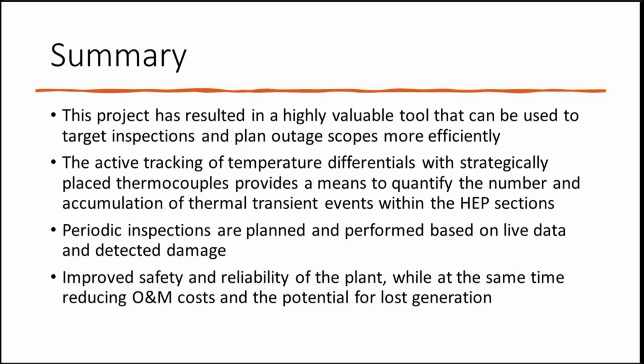The final question from Thane Wade is, is the capacitive discharge welding restricted to piping of a specific material? No, years ago we did the lab work and got the approval of all of the HRSG manufacturers at the time, even under warranty, to use this technique on any material on the tubes, headers, piping, and so forth.